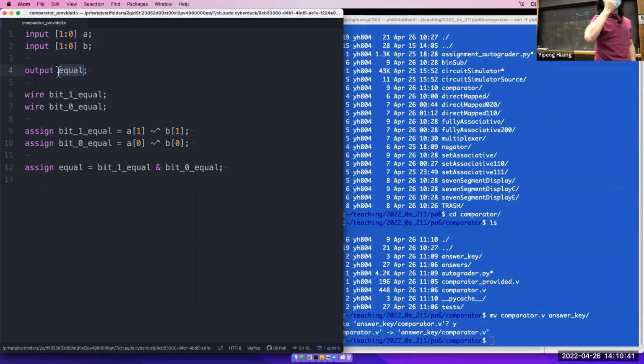It could; there are parts of this assignment where you'll have outputs that have multiple bits, and they'll follow a similar syntax as inputs. Any questions so far about inputs and outputs? Yeah, Donald. If it's a 3-bit input, it would be 2 down to 0. These indices are inclusive, which is a little strange thing about how these things are indexed.